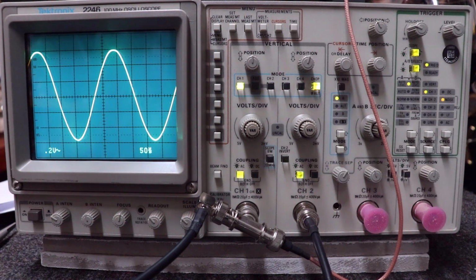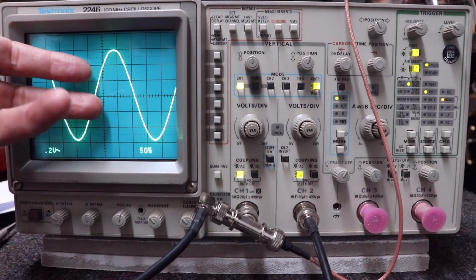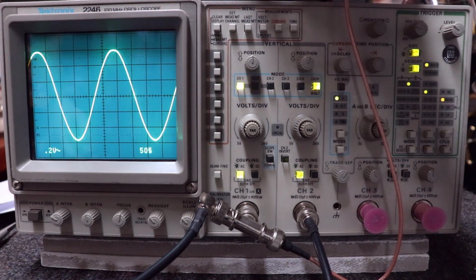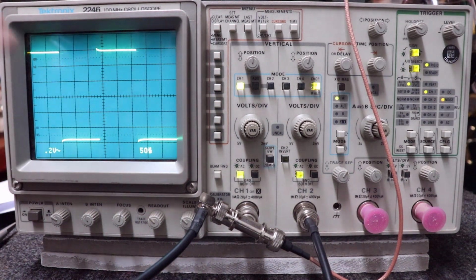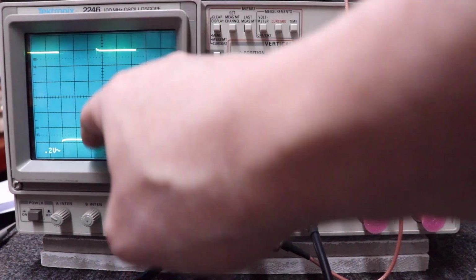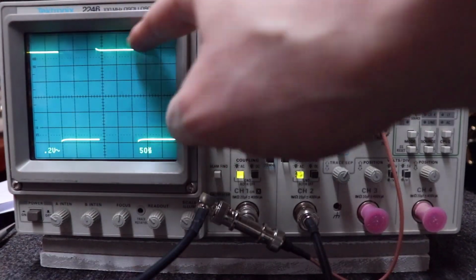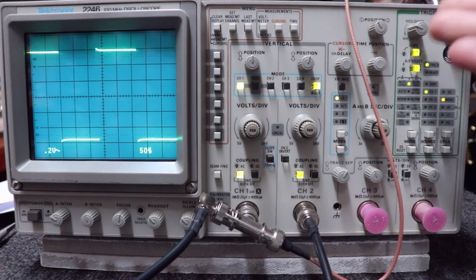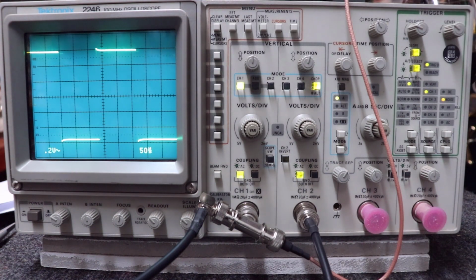Good news is most of our audio testing, we're going to be playing around with sine waves, or we'll be playing around with square waves. And with both of those, it's really easy to lock onto either this up slope or down slope or one of the peaks here. And if you put it in auto, it'll pretty much find it for you and make life really simple. Okay? So triggering 101, not a lot to it after all.